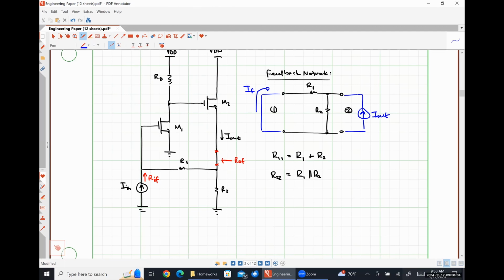So I believe that instead of having a voltage divider here, we're going to have a current divider network. Negative, absolutely. So it'll look like 1 over R1 over 1 over R1 plus 1 over R2, which is the same thing as just negative R2 over R1 plus R2. So just good old circuits 1 level current division. Nothing particularly wild or crazy there.